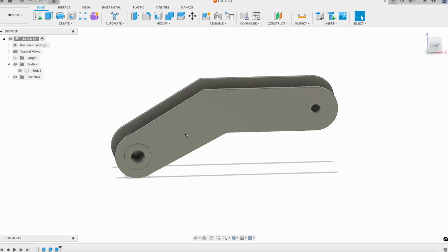However, not the entire object is going to need to have solid material filled in. So what the shape optimization study is good for is finding those spots in the material where the load path does not actually affect it, so you can trim down the shape to avoid wasting material. So we're going to learn how to do that today.